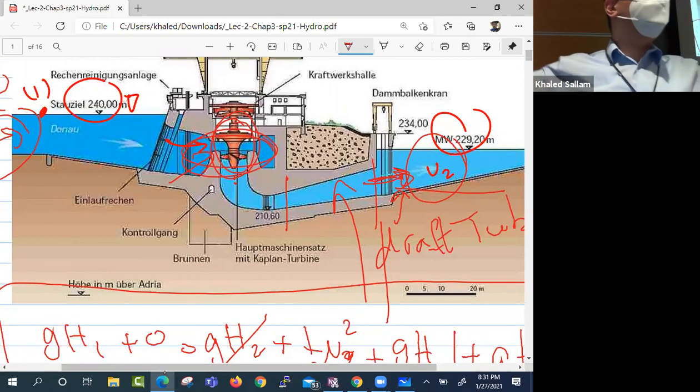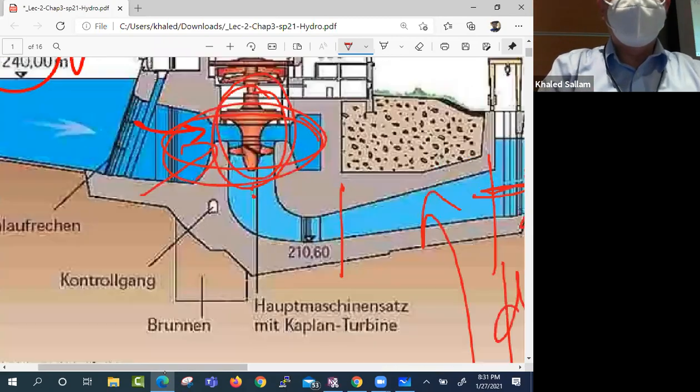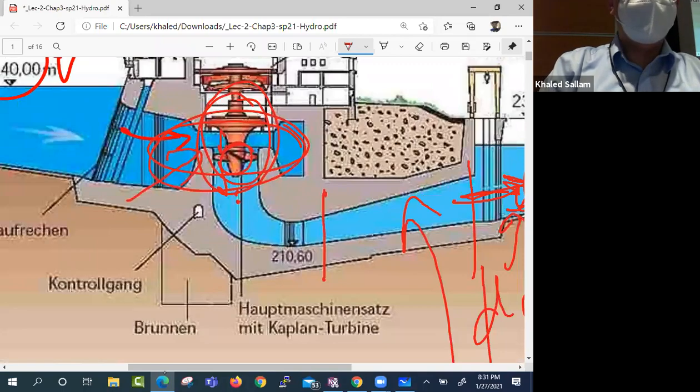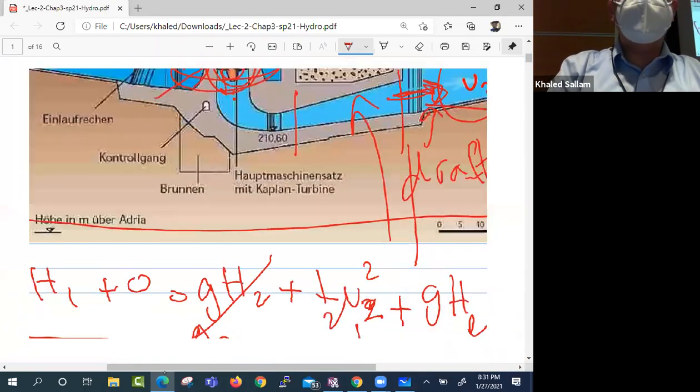The flow coming to that stator is actually in the radial direction. But as far as the runner itself is concerned, the flow came axial and left axial. So it's not the whole machine, it's just the rotor.